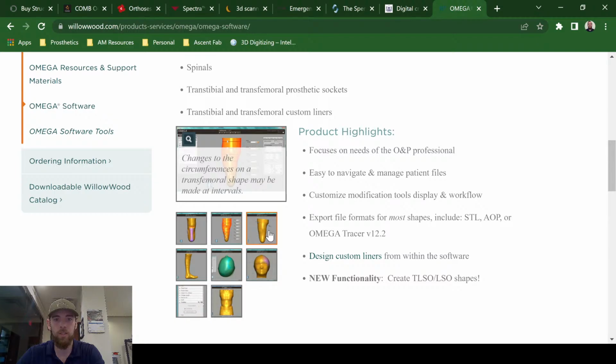And then we have their 3D printer in-house. While we're talking on the side of 3D printers, for the FDM solutions, or FFF, FDM being fused deposition modeling, FFF being fused filament fabrication, those are interchangeable with 3D printing and additive manufacturing. Additive manufacturing is kind of the blanket term. And then underneath that, we have the layering process, FFF, FDM. If you're looking to get into higher end industrial solutions, we also support that at Ascent Fab for selective laser sintering, SLS, or HP MJF with PA12 nylon and PA11 nylon as solutions that you could use for products.